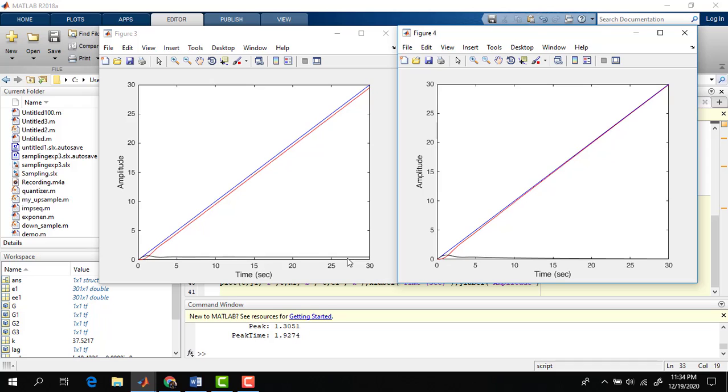But when we are using the compensation, the error is decreased even more, and the error is actually decreased by 10 times, as we have chosen the Z lag and P lag in such a fashion that the ratio was 10. So the error you can see here is very small compared to the previous error. So this was our objective, to decrease the steady state error.